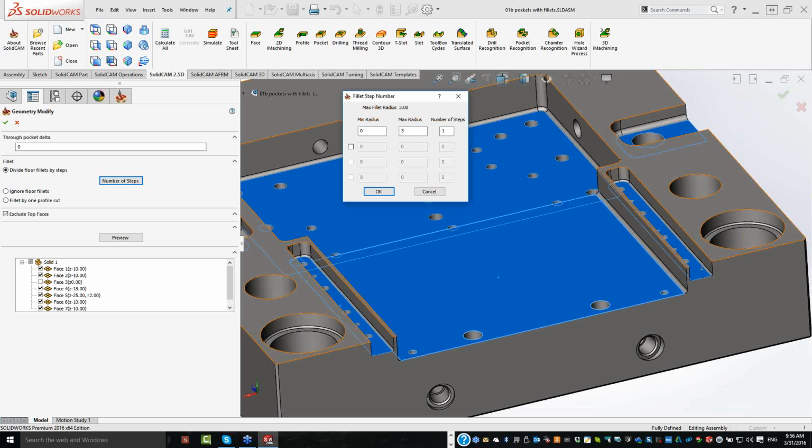So what I can do is open up more fields, and the moment I click on the second field, it'll take the first one, divide it in 2, and then the second one will start from 1.5 to 3 millimeters, and I can say from 1 step down to 2 steps, or change these numbers as well. I can add another one, and then it took whatever was between 1.5 and 3, broke that in half, and made a step down for our next area over here.